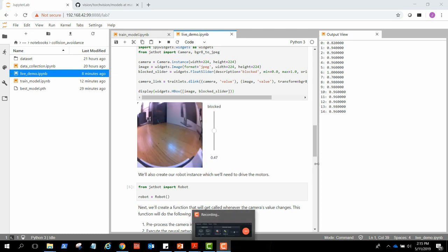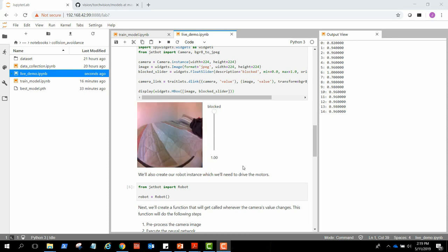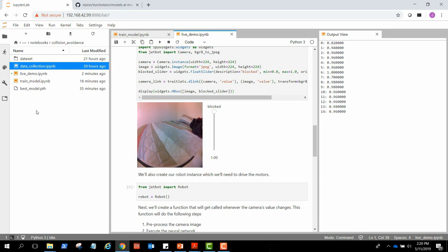But when I put the robot on a different surface, like this more textured hardwood floor surface, it's a little more confused, likely because our training set only included one surface. It's also very confused on this cloth surface, given the textures. I'm going to go ahead and collect different data sets on these different surfaces to see how well the robot does when we add new data into the mix. I'll keep my data sets disjoint so that I can evaluate how well a neural network trained under different sets of data generalizes to sets of data that aren't in the training set.